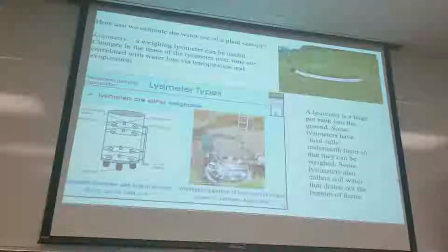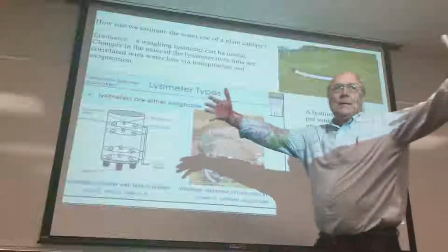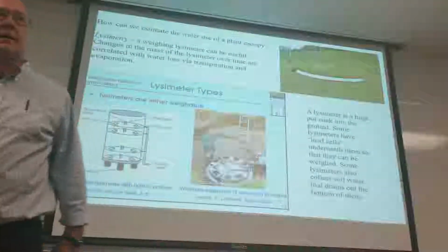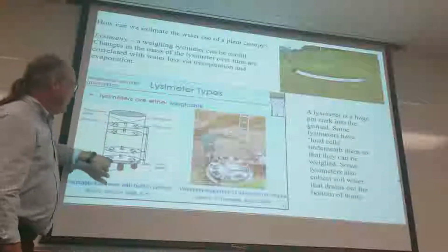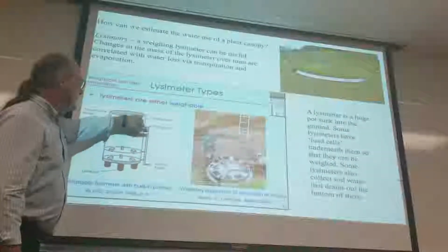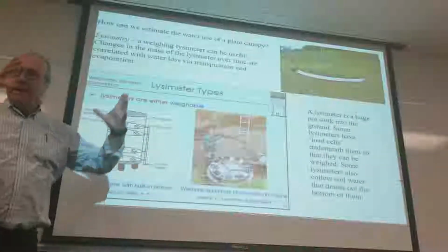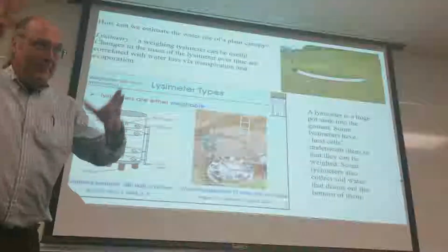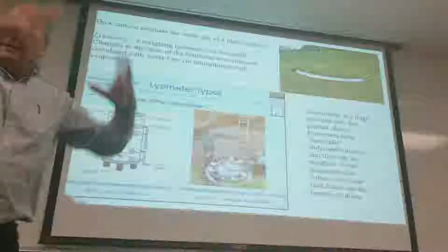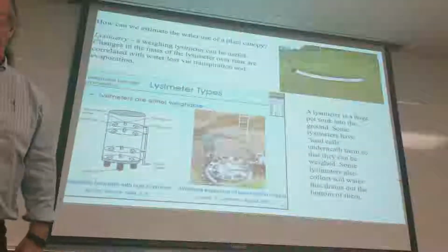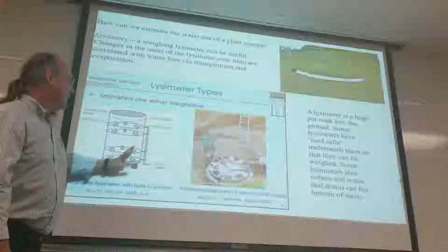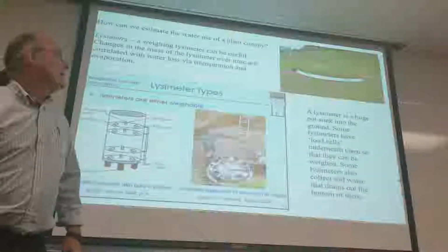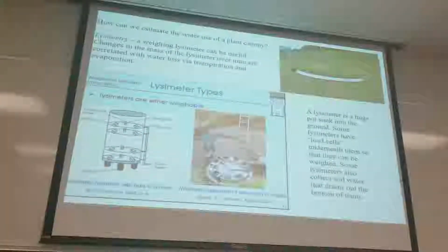So, lysimetry. What's a lysimeter? You know what a lysimeter is? It's a great big pot that you bury in the ground, essentially. It's a big container of soil that you dig out, put in your container, and put back in place. So now you have this monolith of soil surrounded by some sort of container. And what you can do, or what people